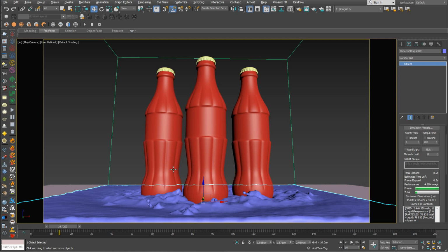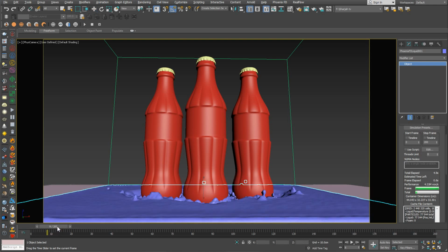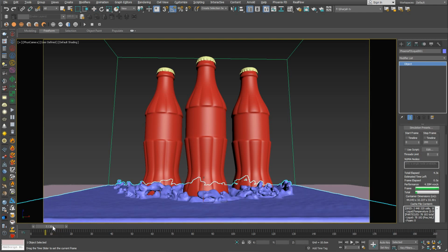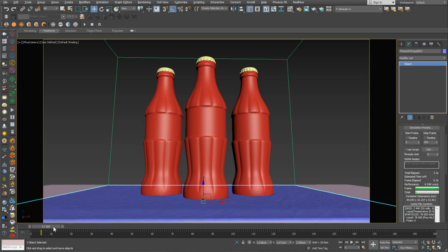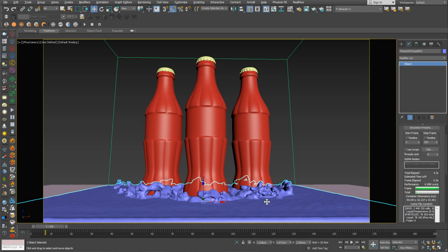Two things to take into consideration here which are really important. The first thing is that the resolution we are working with now is so low, and it doesn't really reflect the actual result we need to expect. Sometimes you work with this resolution and have something nice you like, but when you increase the resolution, it will change dramatically. What I mean by resolution is the cell size. When we reduce the cell size, we will have more particles and the behavior will change. So I recommend working with something mid-ground, high or higher than this, at least closer to the final result.